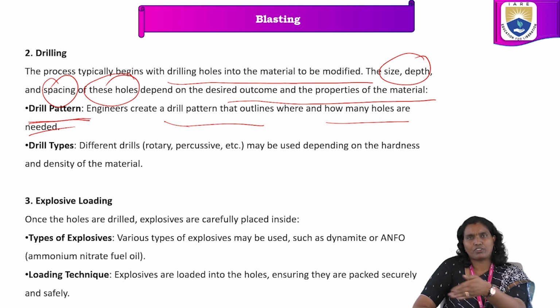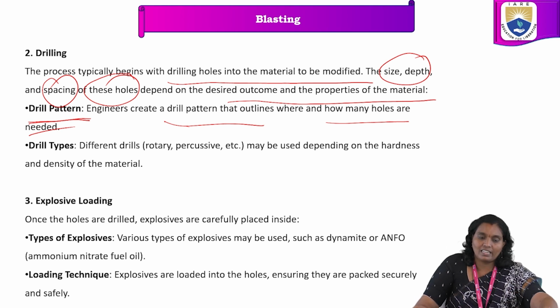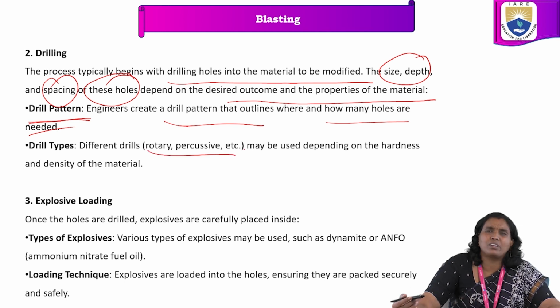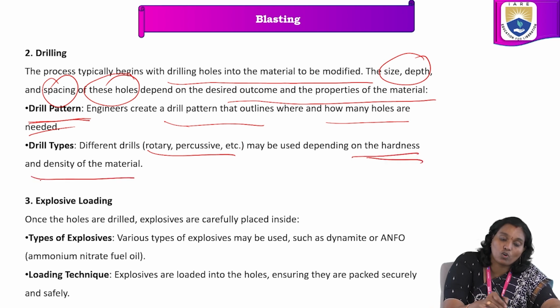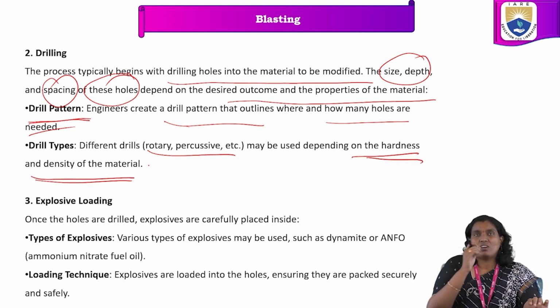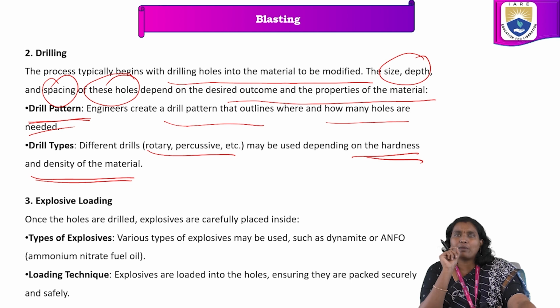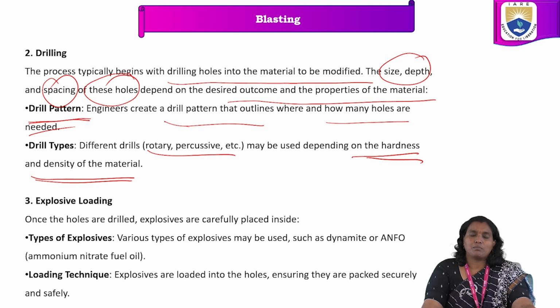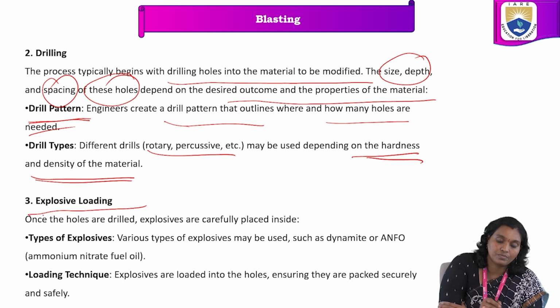Before blasting or after, we have to understand this. There are different types of drills, such as rotary and percussive, which may be used depending upon the hardness and density of the material. Which drill type we choose purely depends upon how hard and dense that particular material is. So, preparation and planning, drilling, and after that, explosive loading.